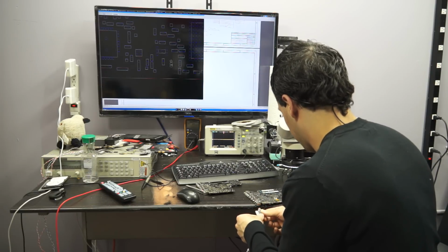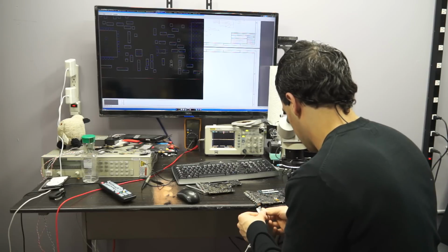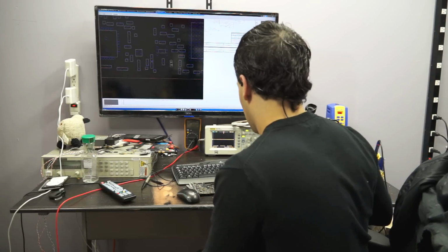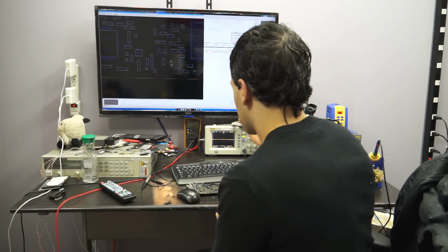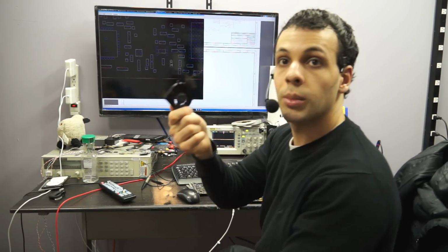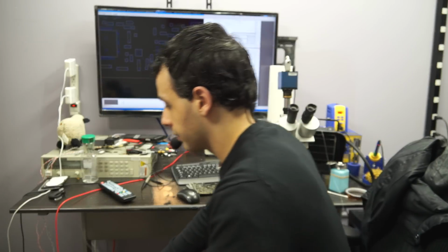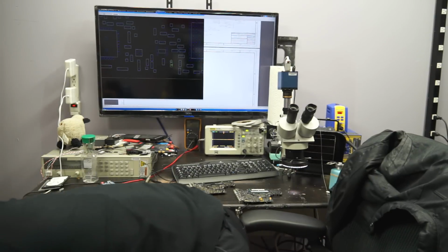So I get a green light, but no power on. It could be no power on, or it could just be that this testing fan that I've dropped on the floor about 90 times a day since moving this desk over here is dead. So let's try the power fan from the actual machine.